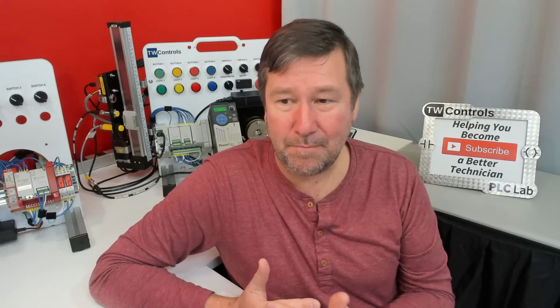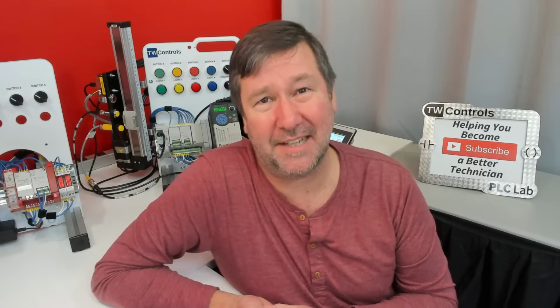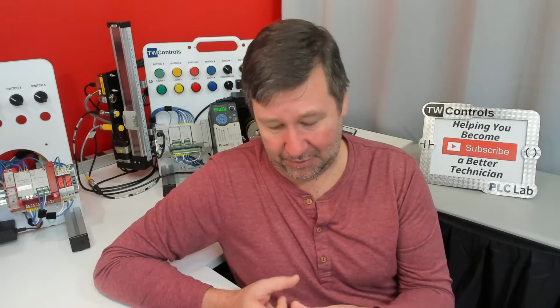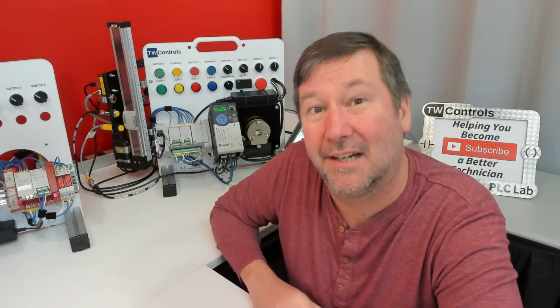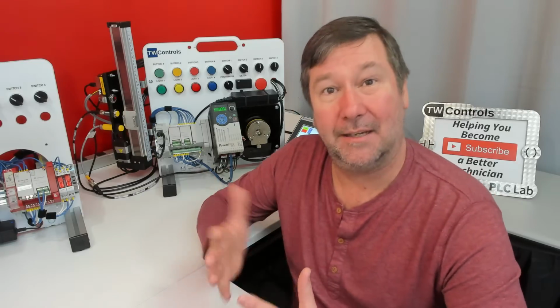The big thing that everyone is deficient on, I feel you could almost say everyone is deficient on when they want to become a UL shop, is torquing and labeling. So right now, maybe you're torquing your power terminals. Every single screw in a panel, including those bolts that hold the panel on, has to be torqued to its specification by a calibrated torque wrench. So that was the big one. And even then, people were like, well, that's going to take me a lot more time to build a panel. Well, you're 100% right. And that's why we switched to push connects on everything.